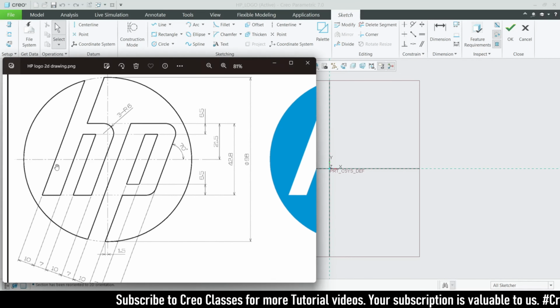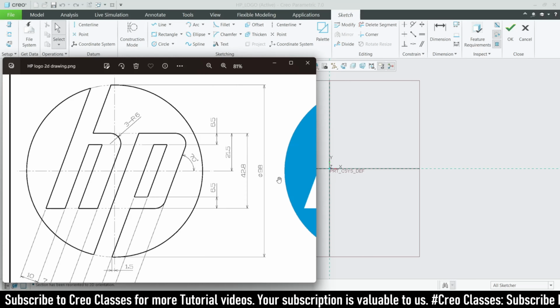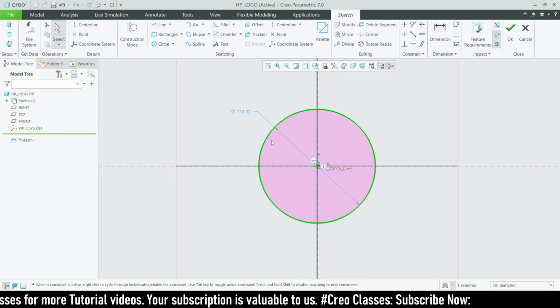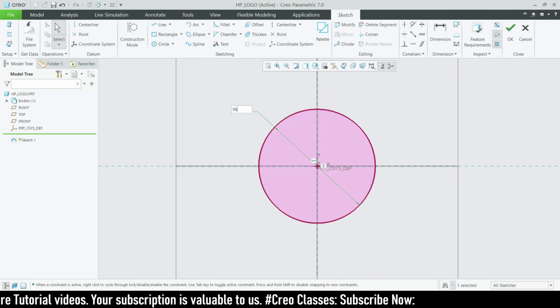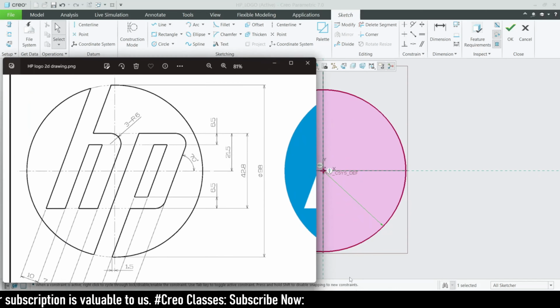Here we have this circle diameter value, right? So this will be 98. Let's draw a circle like this, and this will be 98. This will be our outer circle, and inside this we are going to create the text here, H and P.